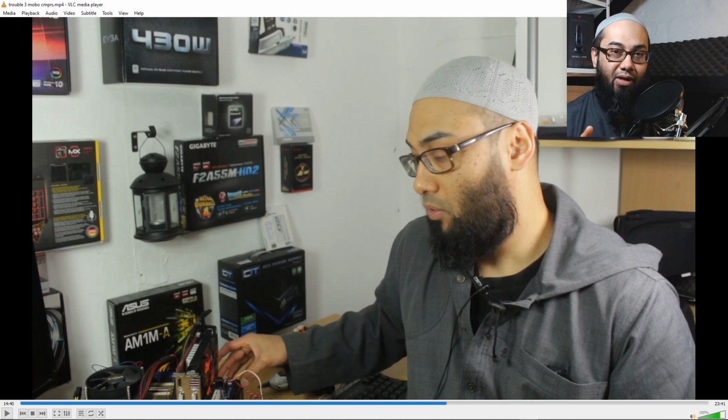Some motherboards do not have LED lights, especially the lower end models, which means you can't really tell by LED lights. And I also mentioned in there that you may see evidence of power. For example, your power supply fan will be turning on. If there is a graphics card on the motherboard, that might be turning on. If there are some other fans or maybe even other LED lights, they may turn on. However, it doesn't mean that the motherboard is working correctly.